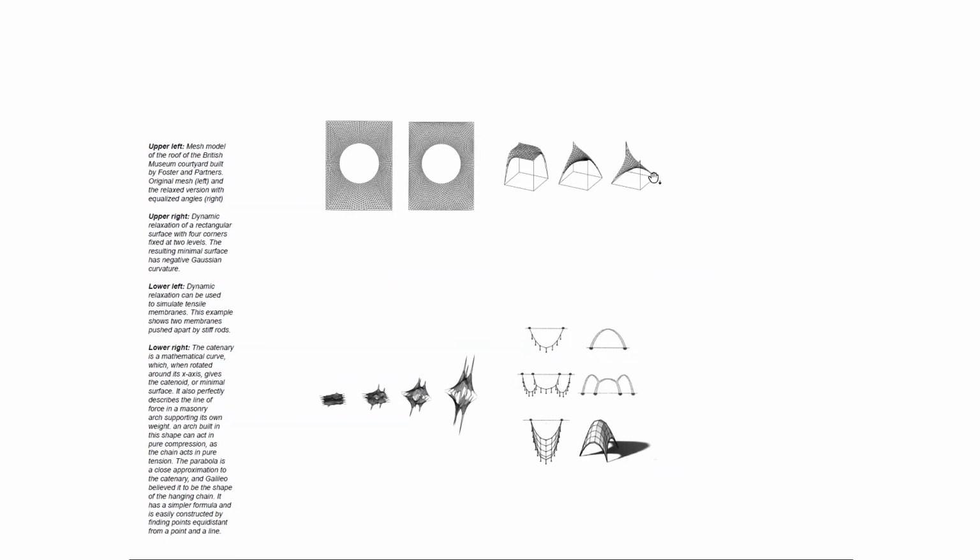Okay, when we have these non-flat constraints, then the surfaces, minimal surfaces, can look a little bit like this, and they're doubly curved. So if you build them out of a stiff material, we can create, for example, thin concrete shells, and because they're doubly curved, they're actually very stiff. So when you look at very lightweight, thin concrete shells, they always have these shapes, and often they are created either as ruled surfaces or somehow relaxed surfaces between these tensile membranes. Okay, so they have application there as well.